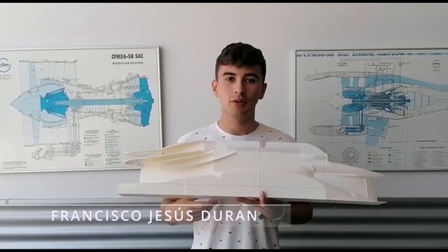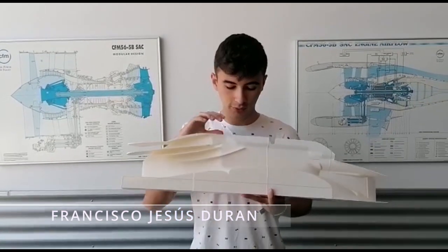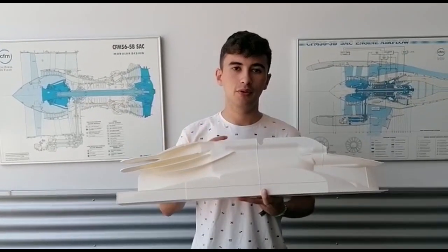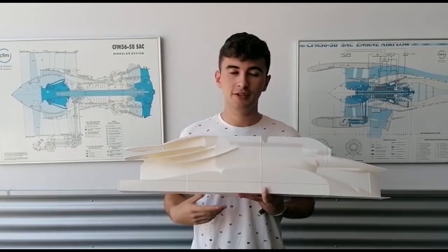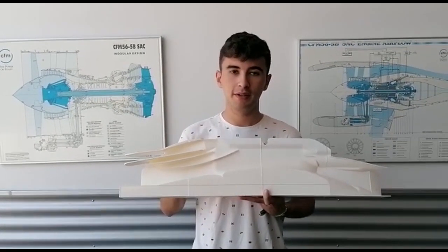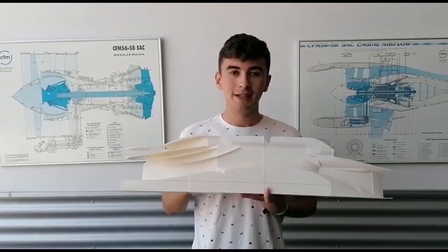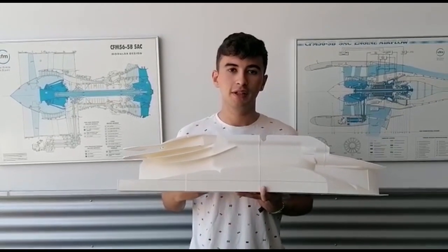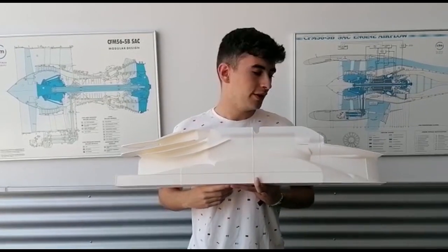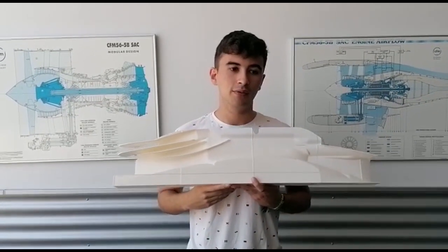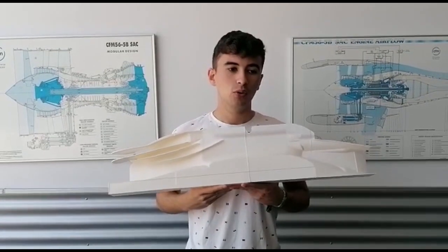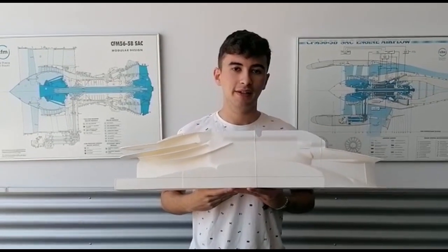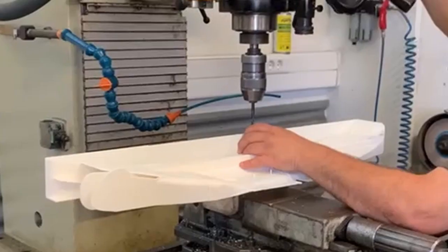Another important function of the floor is to seal the low pressure zone inside it from the high pressure zone outside the floor. This is done with the fins and the vortex generators around the edges, which create a vortex which separates this zone like a dividing wall. This was the same procedure that the old skirt did. Also, the diffuser, apart from decreasing the speed of the flow, changed the direction of the flow upwards, so the turbulent air created doesn't affect the car following behind.